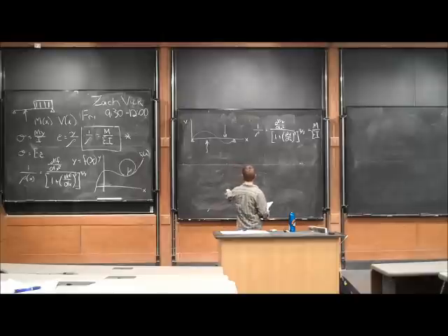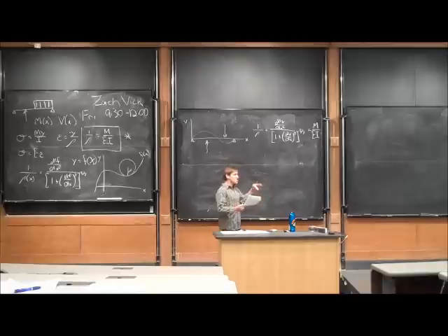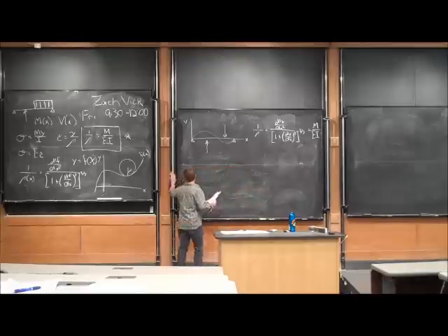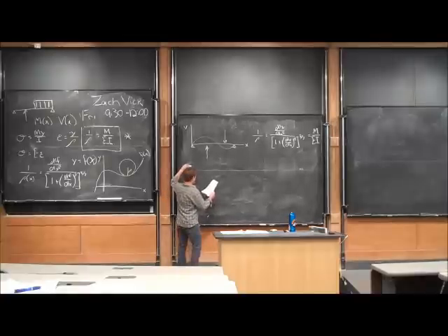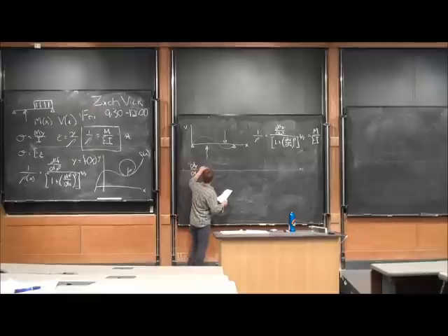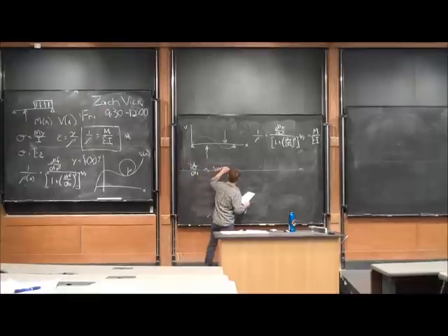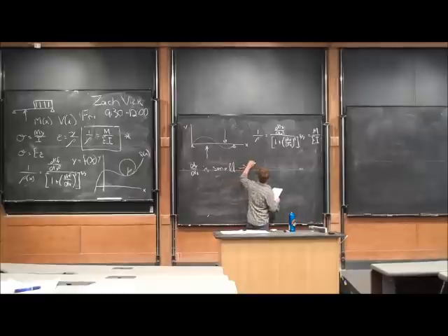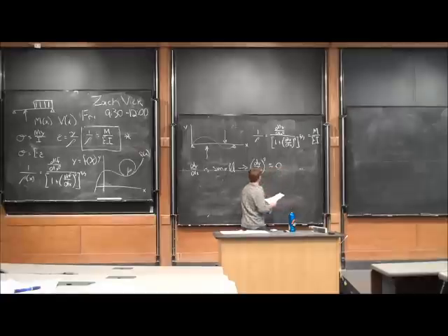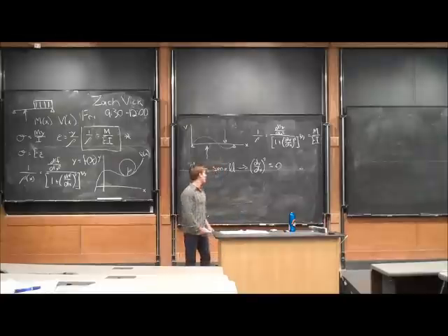And so if we're looking at small deflections, that means that the change in the deflection, or the change in the slope, is going to be very small. What we're trying to say for small deflections is that dv/dx is small, which means that (dv/dx) squared is approximately 0. And if we do that, we get to just delete the entire bottom of that equation, and it makes things a lot easier for us.